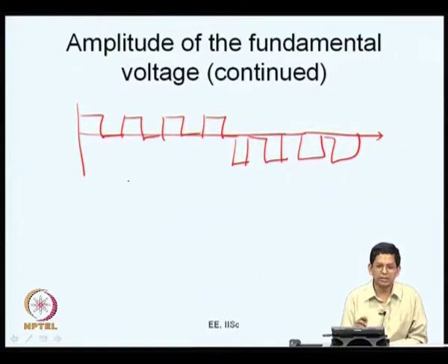In the olden days, the device was switched at very low frequencies. So, in a 50 hertz cycle, one could have very few notches. Nowadays, modern power electronic devices can switch at much higher frequency, particularly if the power levels are not too high, not like tens of megawatts. You can certainly do that now. So, the widths of the pulses basically determine what you want to do. You control the amplitude of the fundamental voltage by doing this.